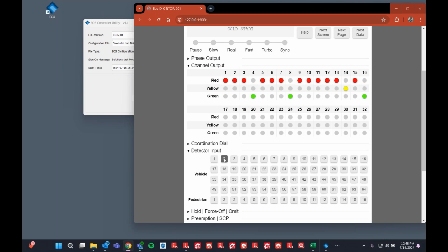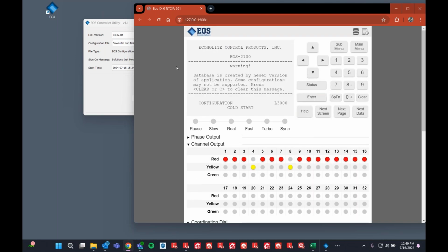So down here you can test it by manually inputting vehicular detector data if you want to try to trip the detector, right? And try to access the minimum green. See, now it's registering a detector call in detector 2, and I don't know, come in and hit some of these until they've hit their call limits. If you want to, like I said, it's not simulating vehicles from Vissim. So if you want to try and overload one of the phases to test preemption outside of Vissim, these are kind of the ways that you would do it. So that's kind of a cool tool, and that's a free open source utility.